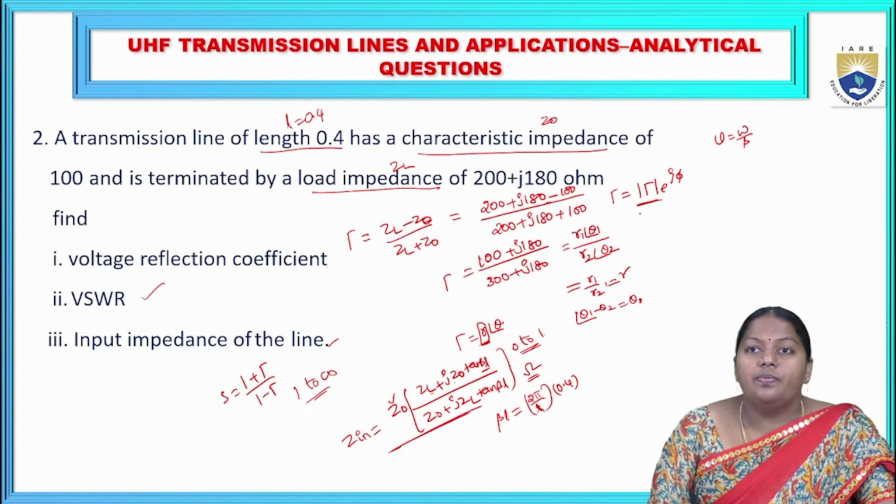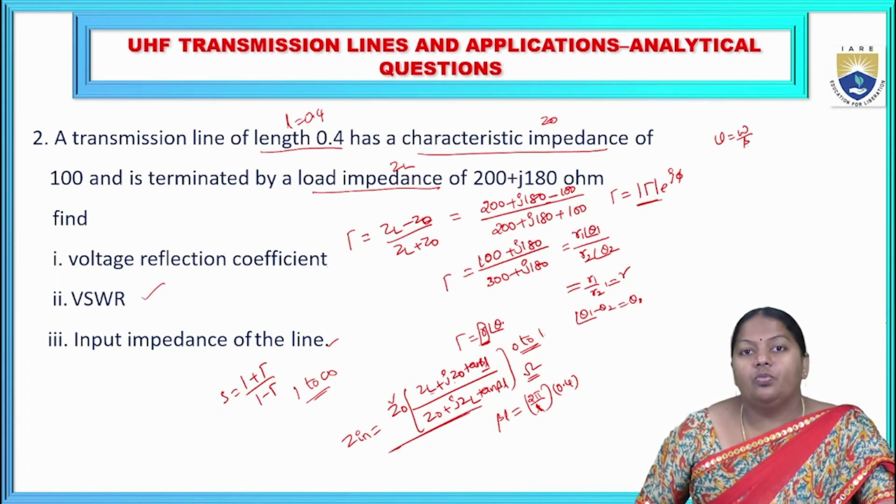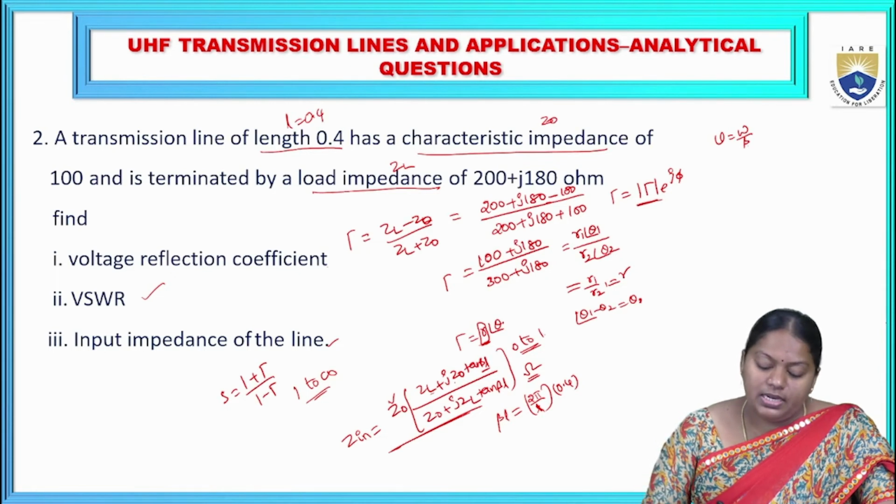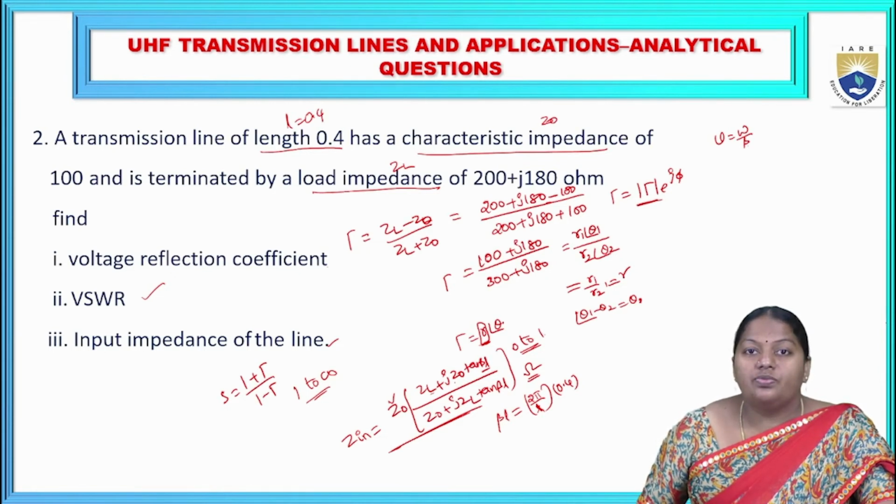First we need to transform the numerator part into polar form, and again the denominator part into polar form. Then the magnitudes of the polar forms need to be divided and the phase angles subtracted. Finally, we get R at an angle of theta. But Zin can be expressed in complex form, meaning x plus jy form. Again, we have to convert that polar form into rectangular form.